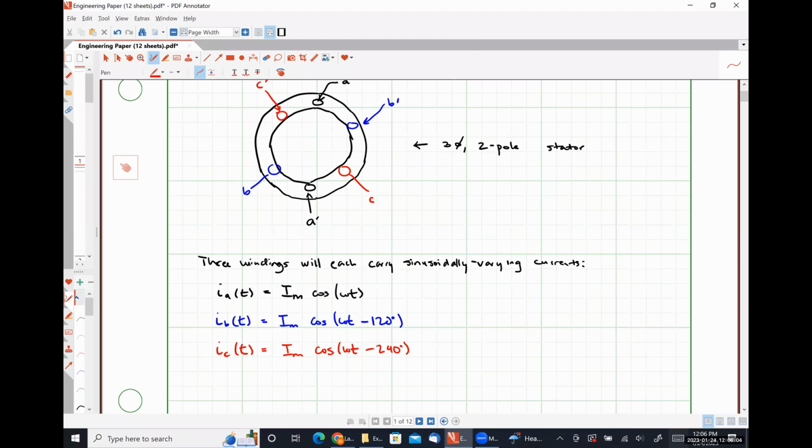We are making an assumption here that our voltage source connected to our stator is a balanced three-phase source, which it has to be unless we physically do something to make it not be. And we are assuming that the load our induction motor represents is also a balanced three-phase load, which it will be, assuming all of the windings have the same resistance, reactance, and all that kind of good stuff, which they should because they're made by robots nowadays.